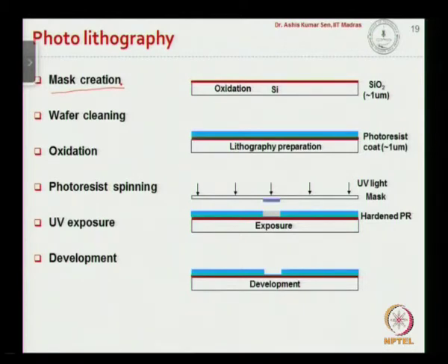For example, if you want to create a channel like structure, as you can see here, depending on the photoresist that you want to use, you may have a mask which would look like this. So these areas may be opaque to light. If you know the edge structure that we want to obtain, accordingly we can design our mask.